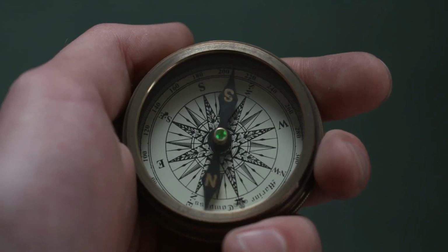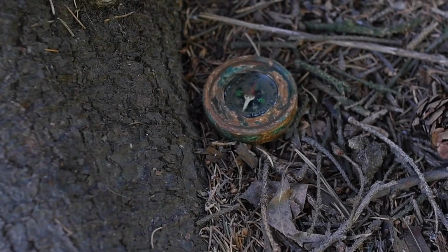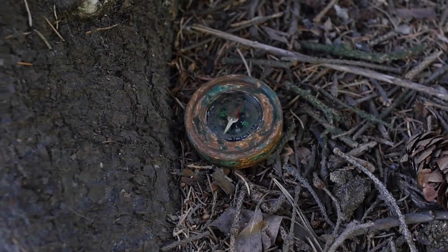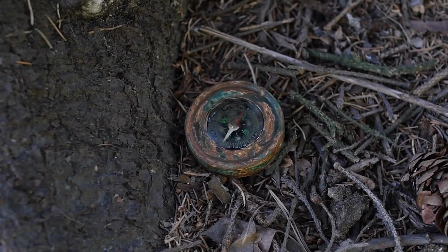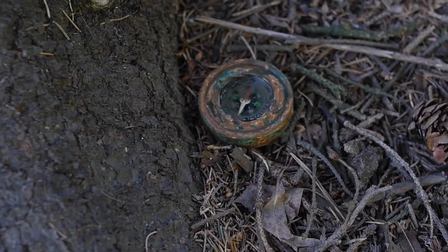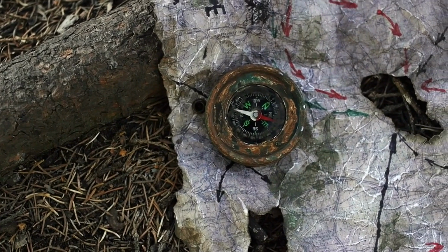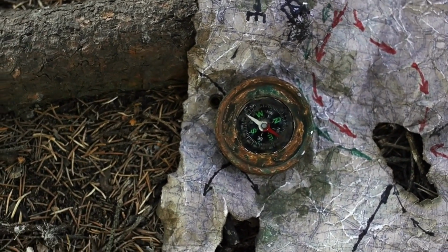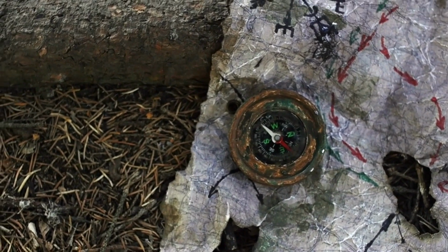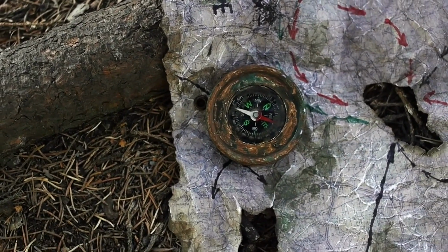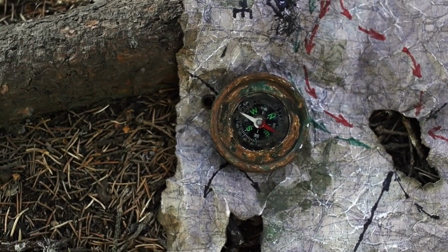The fluxgate compass. This is a simple electromagnetic device that has 2 or more small coils of wire around a highly permeable magnetic material to directly sense the direction of the horizontal component of the Earth's magnetic field. The advantages are that the reading is in electronic form and can be digitized and transmitted easily and displayed remotely and used by an autopilot. It can be sited in an ideal position, low down in the boat and away from any magnetic influences.